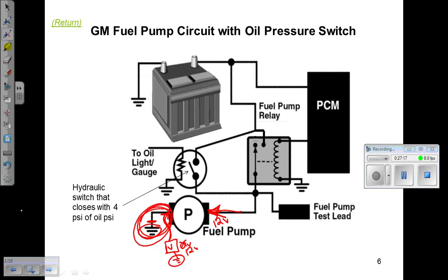And so, yes, that's the way you check the ground. If the ground's bad, you're going to have an elevated voltage. And I'm saying for a fuel pump electric motor, 300 to 400 millivolts would be the most you'd want to see. You start seeing 1, 2, 3, 4 volts or whatever, you're going to have an issue.